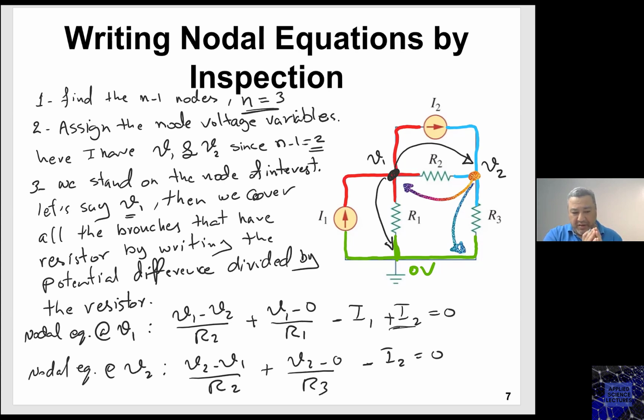And then, Matthias, we came out with this procedure, which basically saves all what we have done to write those nodal equations that we have derived earlier. We've shown you how we derived those ones. Now we have this procedure where we can write the nodal equations exactly the same way, however, by inspection, which has saved us some time of distributing those currents, writing the KCL, substituting those currents with their equivalent Ohm's law expressions.